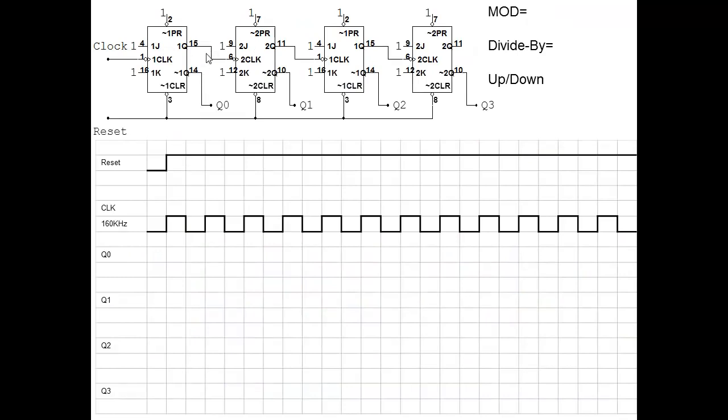And this one, you'll notice, the clock is still negative edge, but this time we're clocking off of Q, but we're drawing Q naught. So for the reset condition, anytime you reset a flip-flop, Q goes low, so Q naught has to go high. So we're going to start high on all these. And the first one is just going to be negative edge, nothing weird going on there. Every negative edge we're going to toggle.